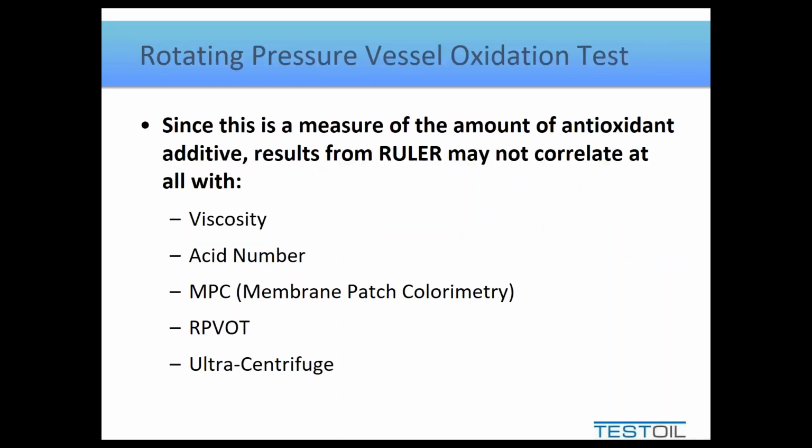Now, since this test is actually a measure of how much antioxidant is present, it doesn't necessarily know how it's going to perform. So that's why it won't necessarily correlate with RPVOT, because that's a performance-based test, not an additive level test. And we've already talked about the other tests. Well, we're just not necessarily going to see a direct correlation.